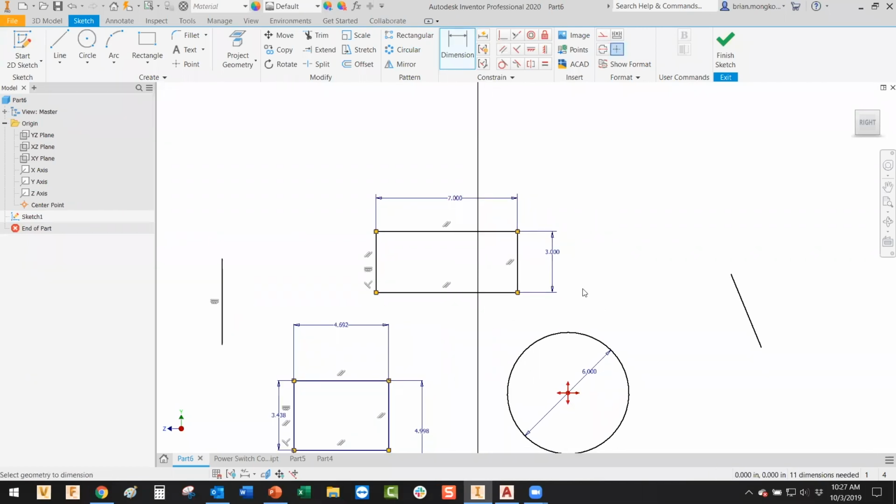If you have a couple of dimensions on your model, you can create dimensions on the fly. So I'm going to create a parameter on the fly. I'm going to call it height. The parameter height that I'm going to create right now equals 7, and the parameter width equals 3.